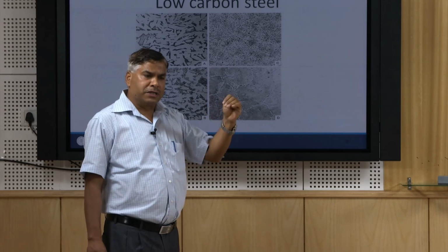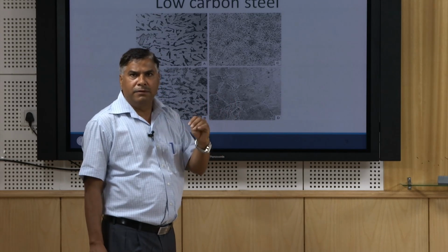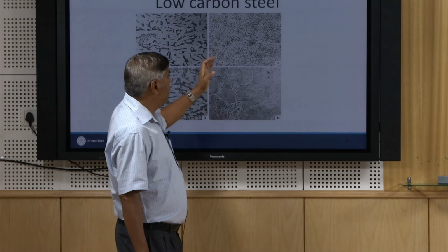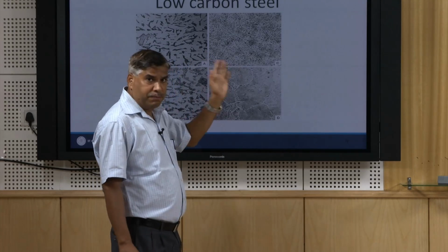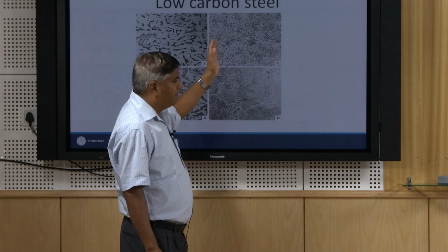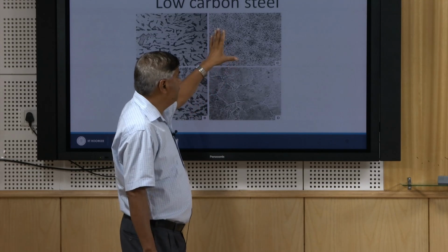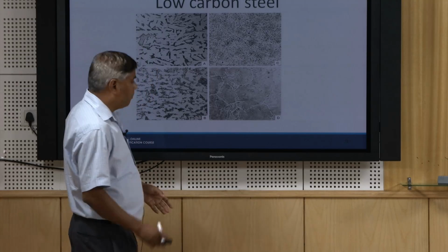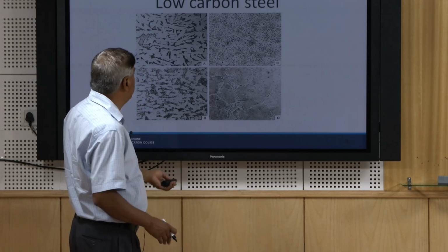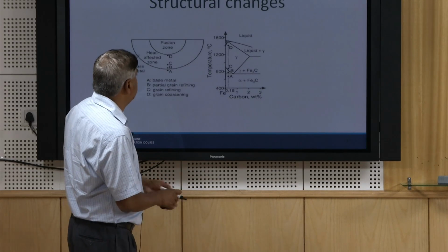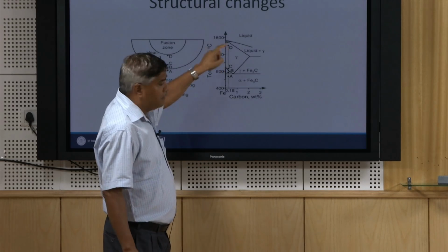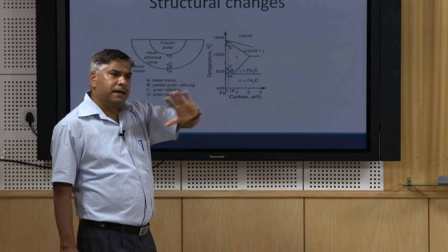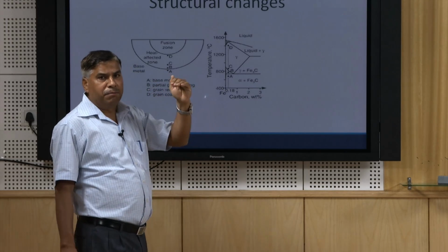So all the ferrite and pearlite will transform into austenite, and that too very fine. So during the subsequent cooling phase of the weld thermal cycle, it will promote a fine pearlitic grain structure. And point D is here, this location very close to the fusion boundary, and it is heated to a much higher temperature for a longer period.